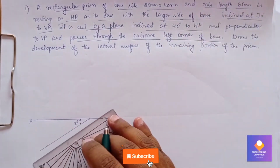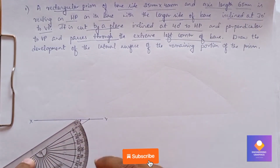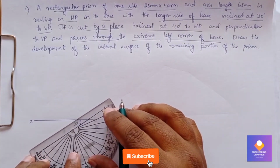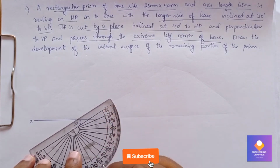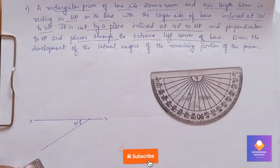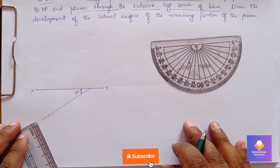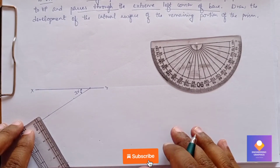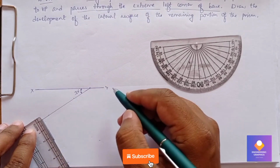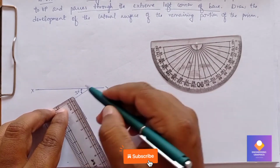Now you take the protractor and mark exactly 90 degrees using these reference points. Again we keep the protractor at another reference point and mark for 90 degrees. Now draw a line passing through this point at a height of 25 mm. It is a rectangular prism. So draw a line passing through this 90 degree point at a height of 25 mm. So you can mark 25 mm here. Then join.